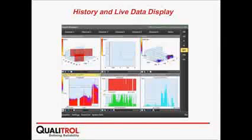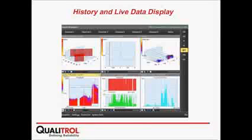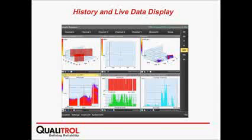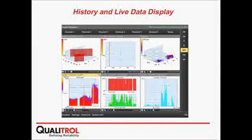This is just a quick snapshot from the actual portable unit. As you see on the top, you have got multiple channels, 6 channels you can look into. And what you see on the left top corner is the live 3D pattern on a 50 hertz system. On the top right, you see the PRPD display with the peaks of the PD event in your system. And then on the bottom side, you see the current status of the amplitude with the historical archive and the event archive on the bottom right-hand side.